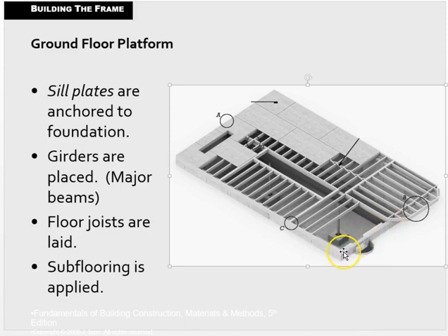But anyway, the sill plate continues above that, and then the girders are the next piece of the puzzle that are put in. So here, the girder would be running right down the center. Right there, we see a column supporting it, a second column supporting it, and then the joists reach from the outside wall over to the girder. A common configuration for a commonly shaped, rectangular building. Like a lot of residences, we'll have a girder running the length of the building, and then the joists will come in from both directions and span to that girder. And then the subfloor is applied here at the top.